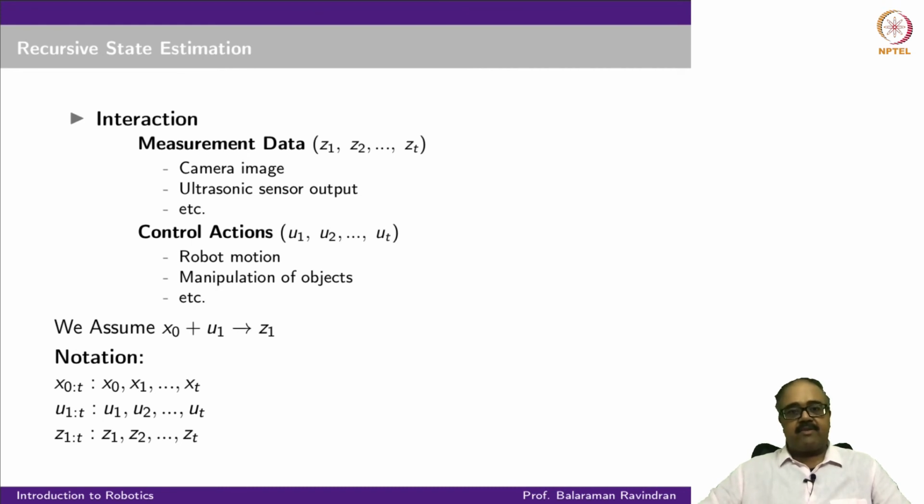All I get from the robot point of view is a set of measurements which I call Z1. So from our estimation point of view, the first set of measurements I get are Z1, and the first action I have performed is U1, but the state I started out at was x0. So Z1 corresponds to measurements made at state x1. Is it clear?